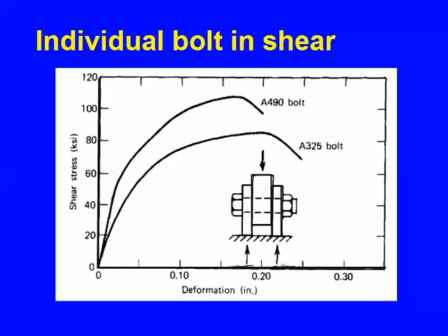What else can we get from this piece of information? Well, the A325 bolt has an ultimate deformation of about 0.2 inches, more or less. That's good, eh? A lot of shear deformation. The A490 bolt clearly is stronger material, not quite as ductile, still got lots of deformation. So we get a lot of shear, whether I'm dealing with bolts or something else. Shear is very forgiving. It's got a lot of ductility in it, just inherently in how it's happening. So that's good information, a good basis upon which to write a rule.